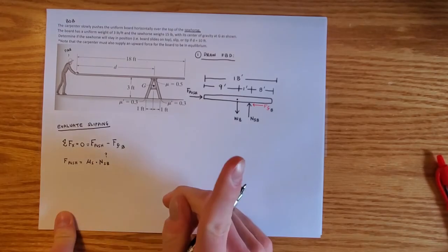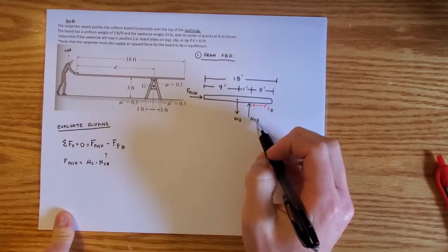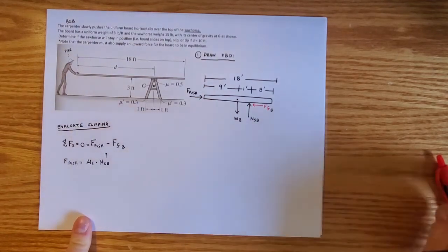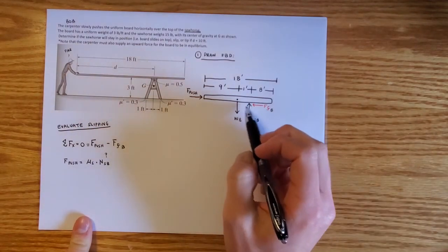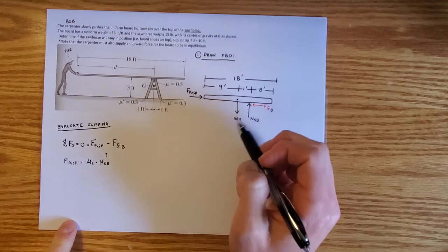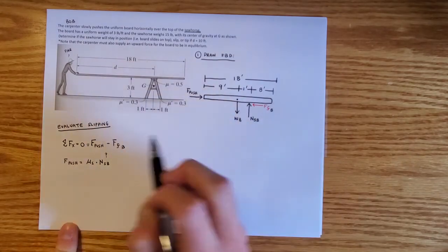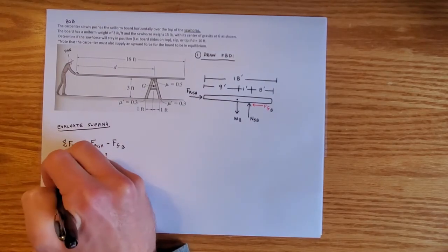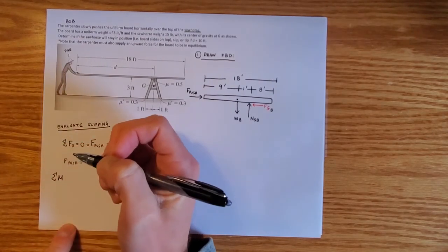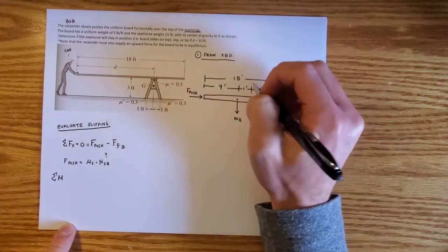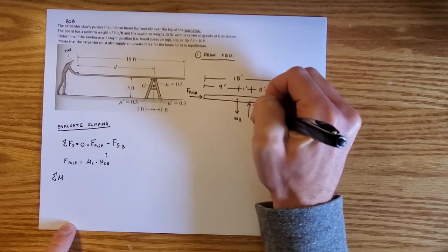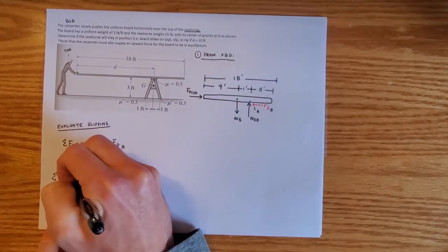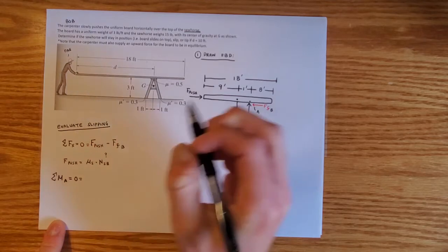It might be tempting to say, oh, the normal of the sawhorse on the board is going to be the weight. And that's exactly what the person who wrote this problem wanted you to do, to fall into that trap. But look, these things are offset. They don't pass through each other. So we can't just do a sum of the forces in the y direction equation to figure this out. We actually have to do a sum of the moments equation to figure this out. So what I've done is I'm calling this point A, which is the contact point with the sawhorse. So the sum of the moments about point A is going to be equal to 0, is equal to the weight of the board.